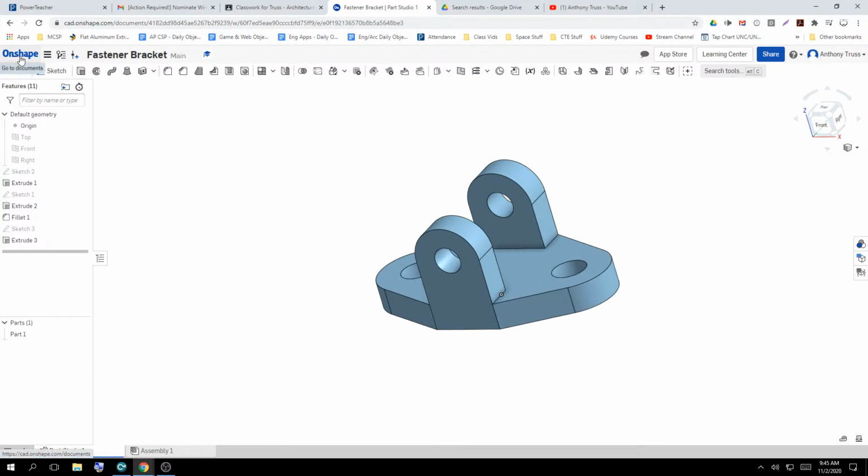So understanding the concept of radius being half of the diameter is important. Understanding that when it says drill a hole, it's specifically mentioning a diameter measurement, because that's how drill bits are measured. And then just dividing and finding the middles of numbers is pretty much the key to this.